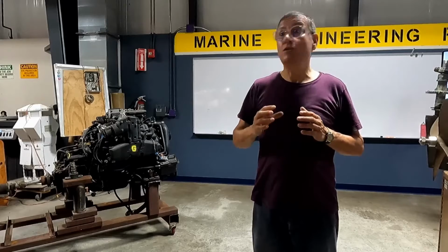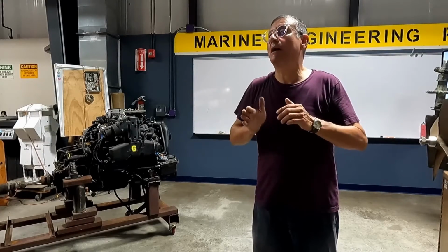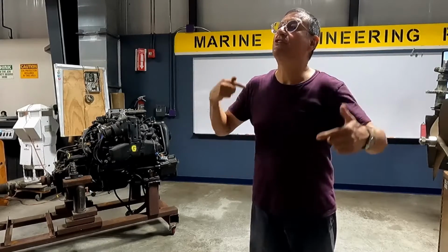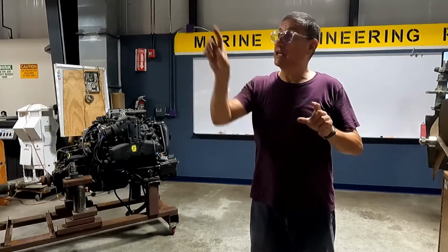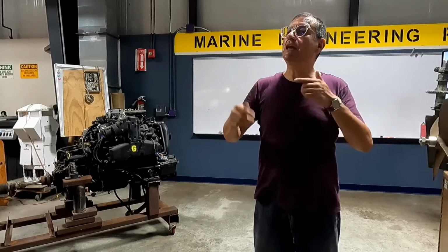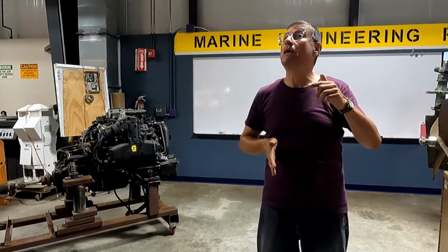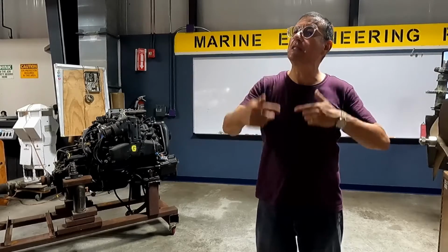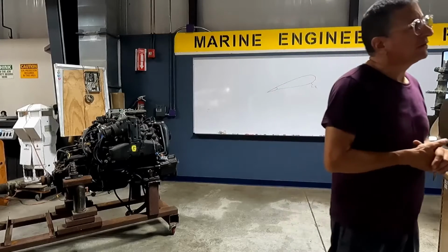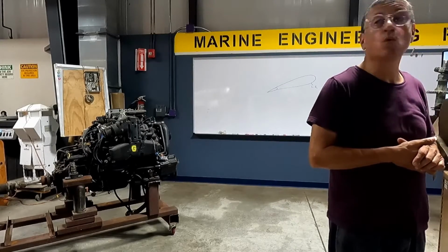In this particular case, they don't add pieces of metal on the blade. They remove a little amount of material from the opposite blade until the balance is perfect, the dynamic balance. And the screen I showed in the video indicates where you need to remove it. In the opposite blade, you need to remove 2 grams, 3 grams. They remove material until the balance is perfect. Yes, just like grinding some down off the base. Nice, no? It's nice work.